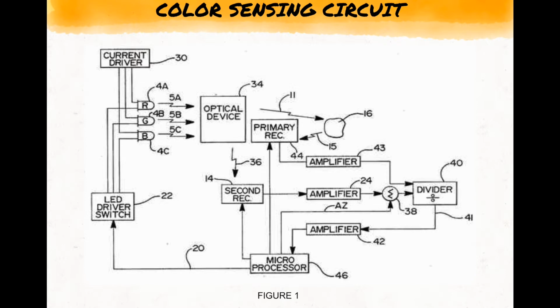According to the present design, the light emitted from the light sources is carried to the object of the color to be measured using a fiber optic bundle. According to one embodiment of the present design, a portion of the fiber optic bundle is split off and directed back towards a secondary receiver, which measures the light output from the split off fiber optic cable and then uses that signal to either regulate the output of the light transmitters and or make correction for drift of the output of the light sources in the calculation of the level of reflected light from the object whose color is to be measured, and the use of an ultra-zero signal to prevent electronic saturation when the light sources are off.